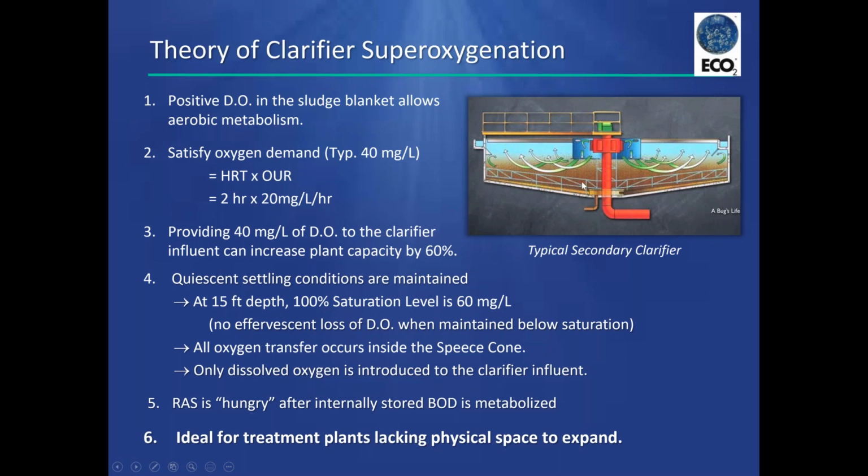If they were, of course, we would get dissolved air flotation and we would ruin the whole process here of gravity settling. So by doing this, the sludge now has another opportunity to aerobically metabolize, so that when the returned sludge is brought back to the head end of the aeration tank, all of the stored BOD has been removed.